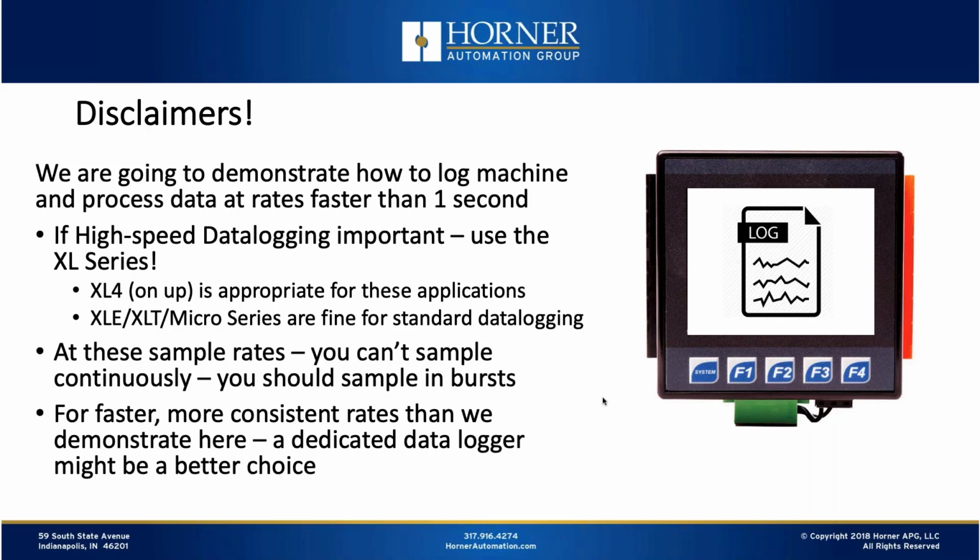Because at these sample rates, you should also consider the fact that you really can't sample continuously. If you're going to be taking data, let's say every 20 milliseconds or so, you aren't going to want to be doing that on a continuous basis. The high-speed data logging you're going to want to do should be done in bursts. Maybe during a certain part of the machine cycle, or maybe when you want to run a special test on demand, those sorts of scenarios. You're not typically going to do high-speed data logging continuously.